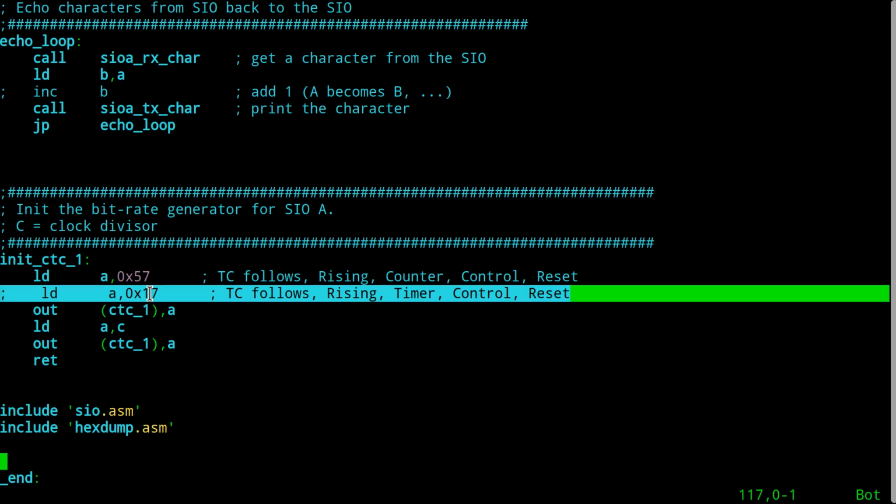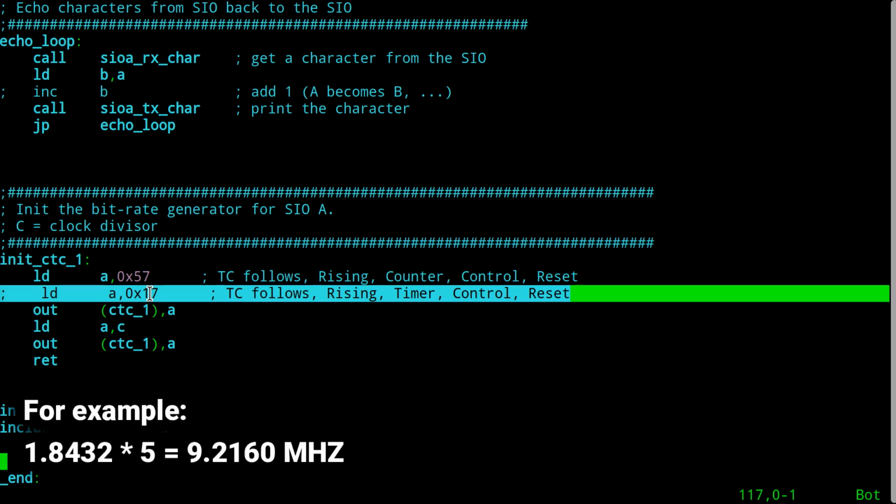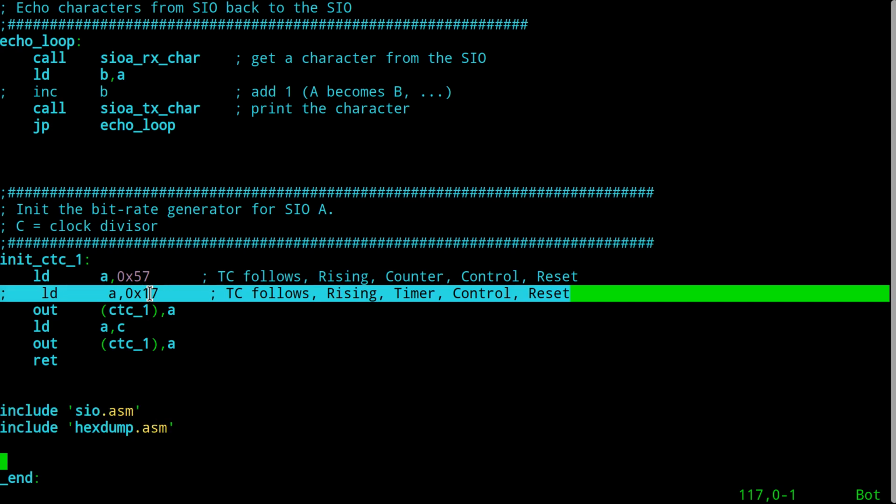Honestly, my original version 1 of this design used a single oscillator that ran at like 9 point some odd megahertz, which is almost 10 megahertz anyway. I mean, performance-wise, it would have made no difference. But the problem is I couldn't get the oscillator, they were out of stock. So I couldn't find one. So I just said, forget it. I'll just use two separate cans, and then we all have the option to go either way.